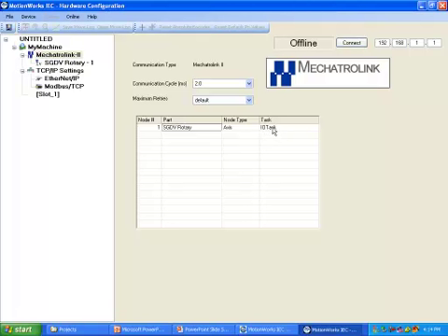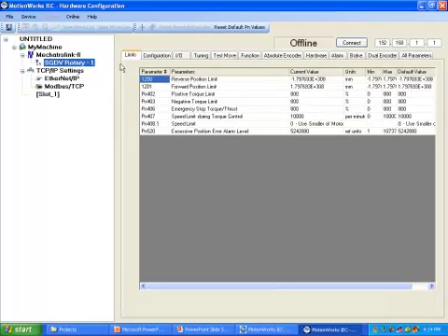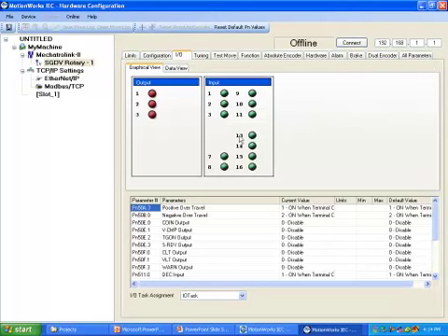But please don't think that you need to use the I/O task for your I/O. This is just a default so that when you do have a new project, your I/O does run on a task. You're always free to come in here to the configuration and then update that through the I/O tab and change that task to any of the other tasks that are available.